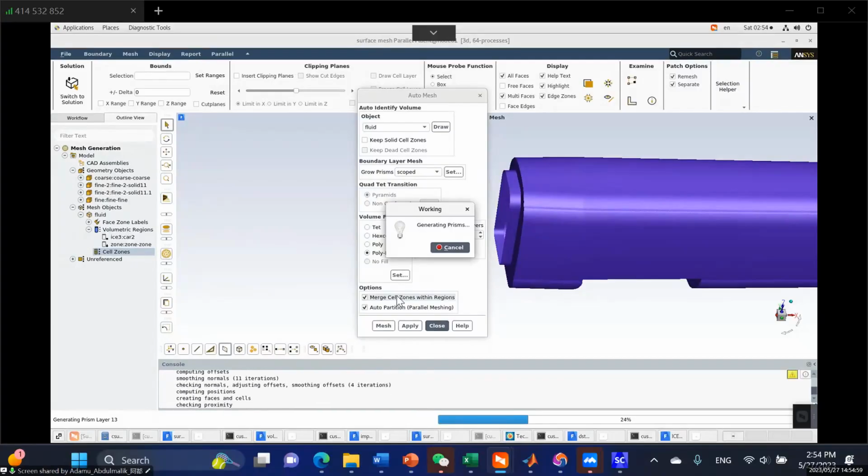So these are the various operations you are going to do when generating the computational mesh, right? So the first thing we need is to generate our various components, okay, which is the train model, the computational domain, and the body of influence.